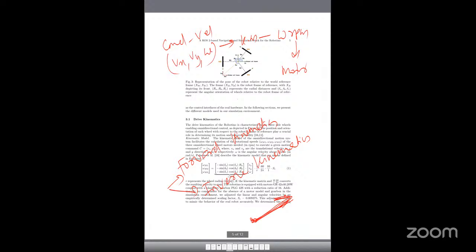In the motors in Robotino, every motor has an incremental encoder. The encoder will measure how many times the motor rotated, and also the speed. For example, wheel 1, say 120 RPM. Wheel 2, 118 RPM. Wheel 3, 125 RPM. So the encoder will measure all those things.